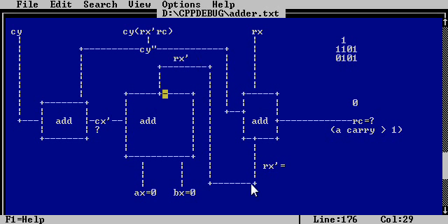And it comes down here, and it goes into this adder, which gets added to 0, and its output goes out here, which is 0, and it has no carry, and that's done. And we have no carry coming out here, so the input into this adder is nothing, and there's no carry. So everything comes out 0. Great. So the first part works.